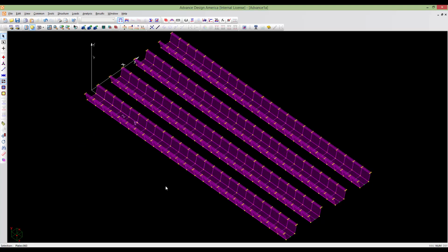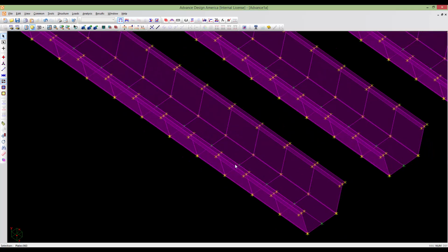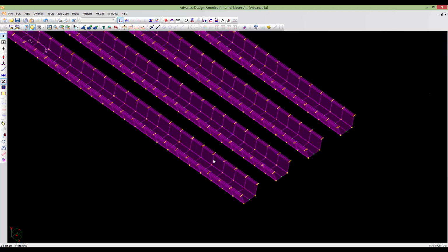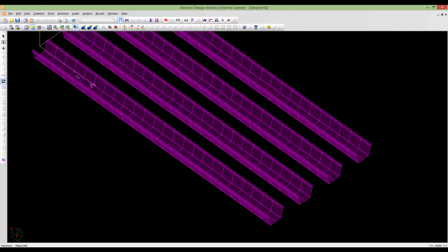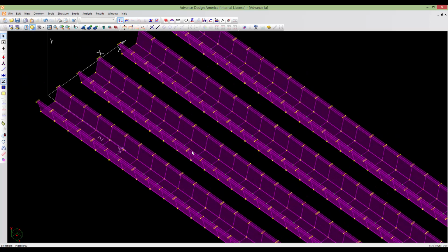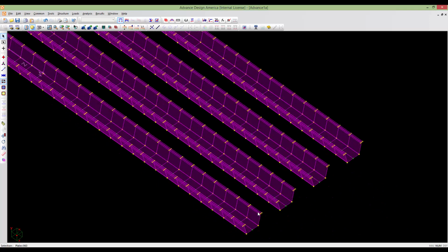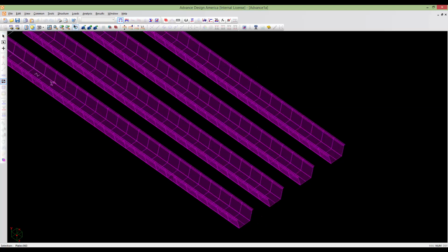and if you see right now, as you see, I have just the finite element plates of steel box girders. I don't have the concrete yet. I mean, I've hidden it. So right now it's easier to put these transverse, extra transverse members to use them as lateral supports.